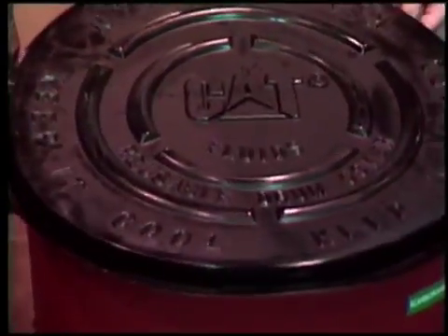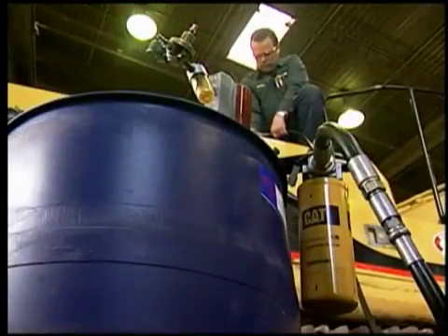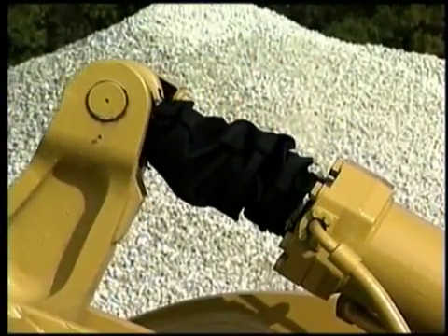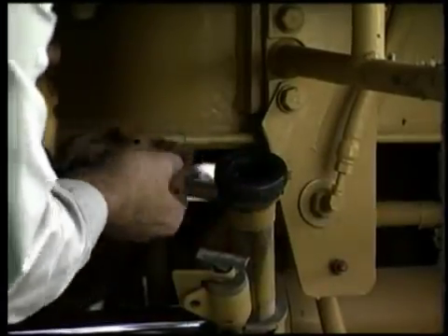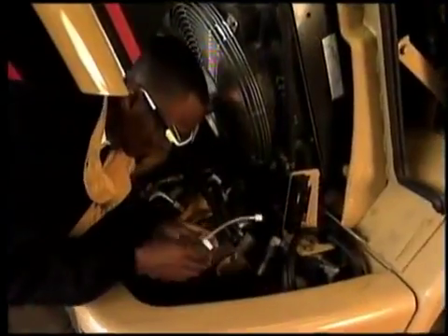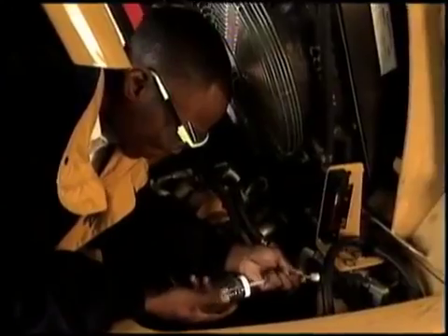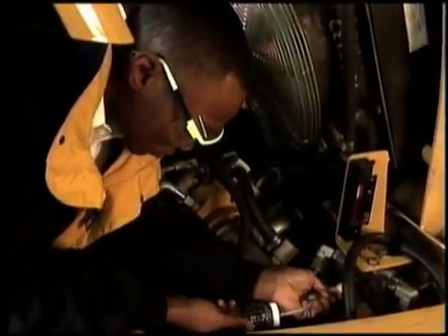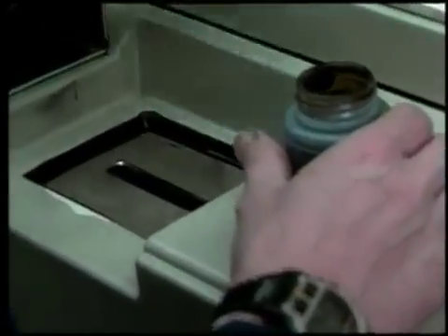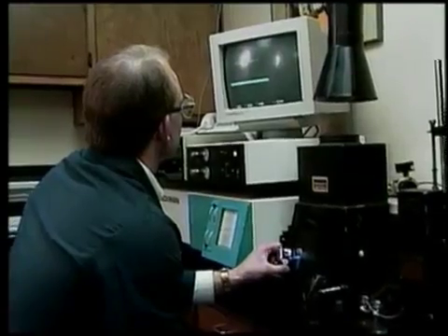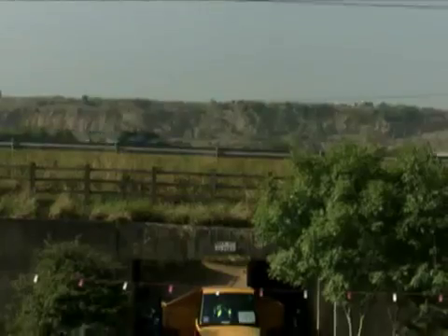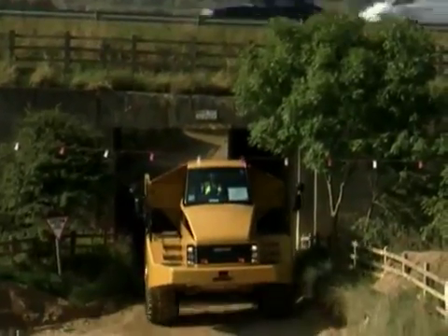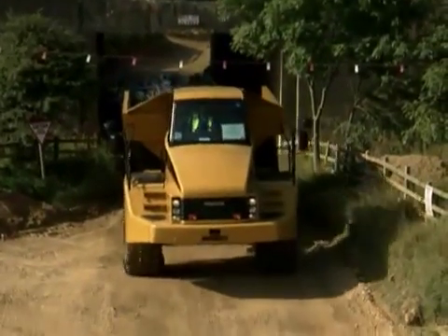Store fluids properly. Filter all fluids. Protect machines during operation, and during preventive maintenance. Take oil samples at the recommended intervals using proper techniques, and regularly use particle count technology to monitor and trend contamination levels. Contamination control is no longer an option.